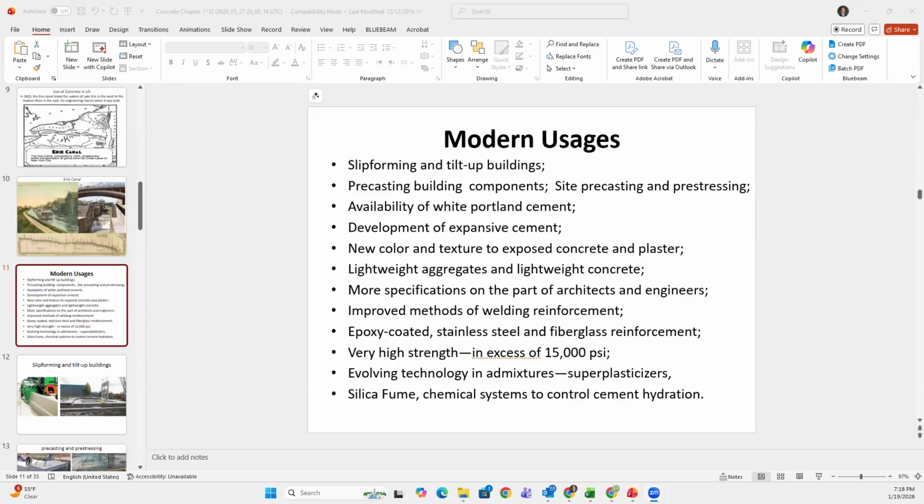Now, if I can get the concrete to 110 pounds per cubic foot, is that good? Human beings have learned how to make strong concrete by using special lightweight aggregate and bring the weight of the concrete to 110 pounds per cubic foot. That's what we call lightweight concrete. It's still heavy, it's still 110 pounds per cubic foot, but your building all of a sudden is one third lesser weight. So, Professor, is it done with the same materials that you told us in the beginning, or is there some other type of material?